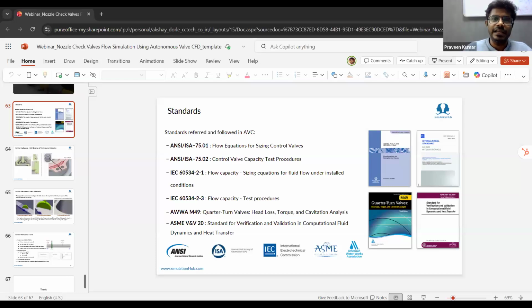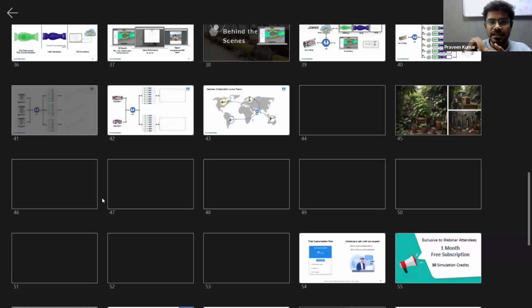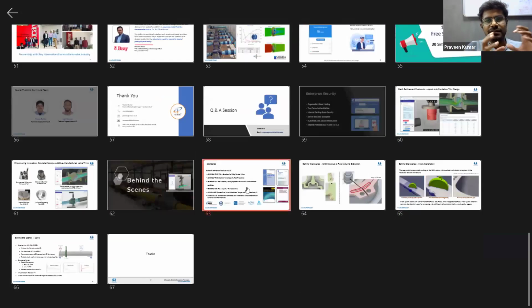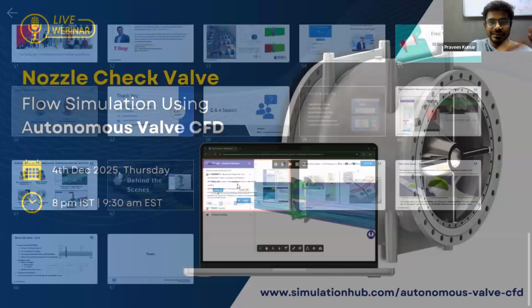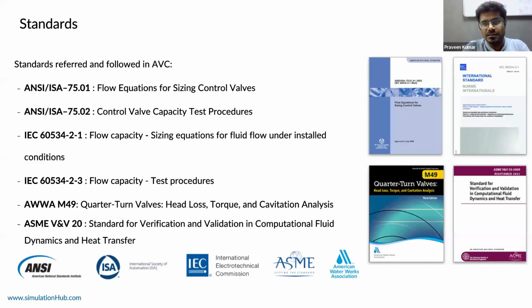I'm there, 63, yeah? Meanwhile, we got that question in English. Is there a mathematical model to determine the hydrodynamic force that has been got from CFD? Not really. The CFD simulation directly gives it; it's a post-processing technique through which we can get this hydrodynamic force. I'm not sure there is a separate mathematical model other than CFD. Once the CFD simulation is done, the results are there. It's just a post-processing tool which can extract the surface integrals and hydrodynamic force of the moving bodies.